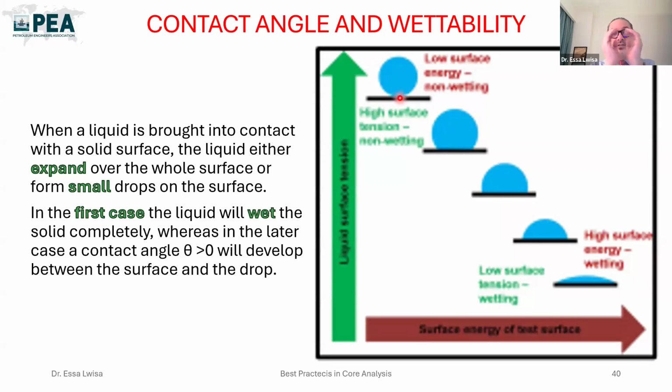Okay, so it takes the spherical shape because the drop wants to keep the contact between itself and the surface as minimum as possible. But when the drop loves the surface, then it will hug the surface. It wants to make the contact surface as big as possible. So here, if you want to measure the contact angle, it is obviously higher than 90. It's almost 135. But here the contact angle is like maybe 15.